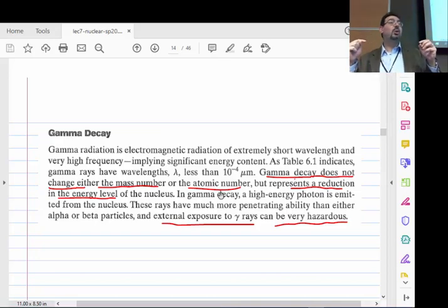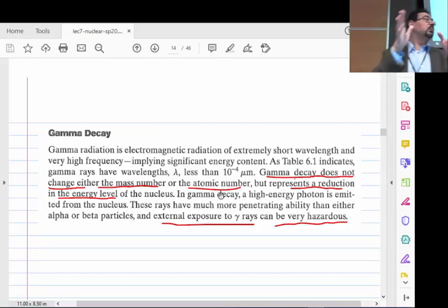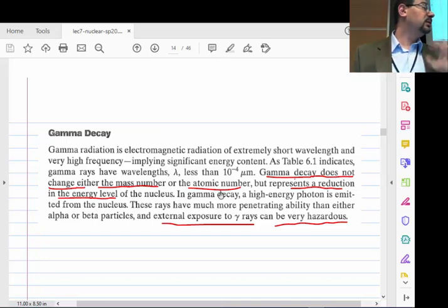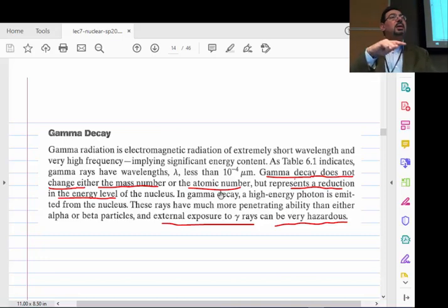If all the radiation goes through, that's one thing, but if the radiation is being blocked, you must have a lot of liquid. They send the gamma radiation at different levels and receive the signal, and by figuring out how much attenuation or loss in the radiation there is at those 3 different levels, they can tell not just how much liquid and how much gas is in the pipe, but whether the liquid is oil or water, for example.